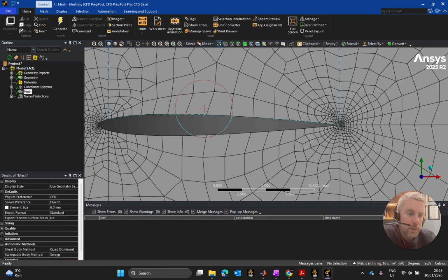So spend the time on it. If you have a week to do a CFD analysis, 3 days you can spend maybe tuning your mesh and making it better, and so on.